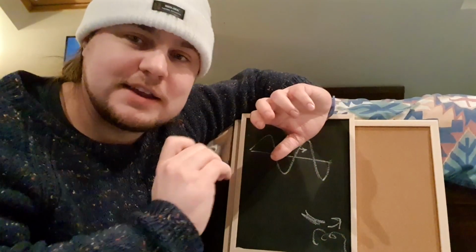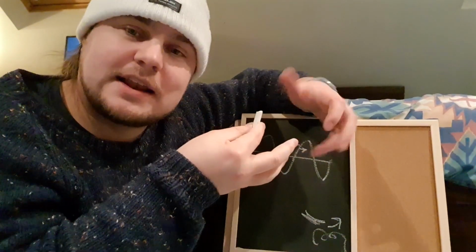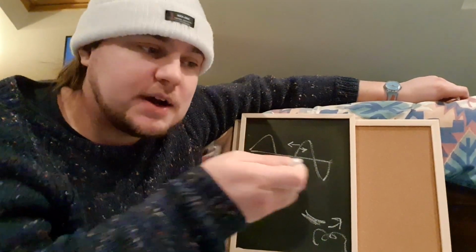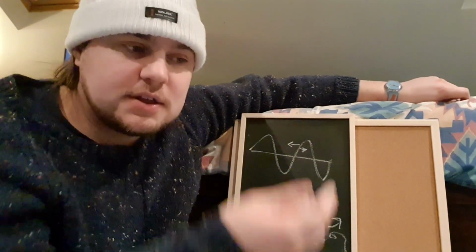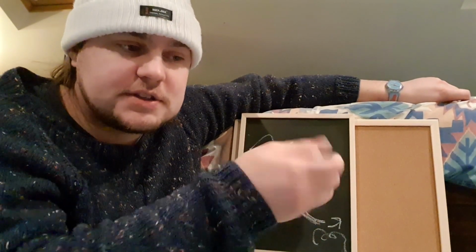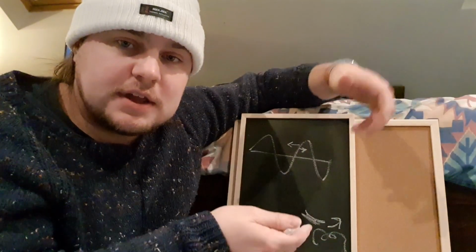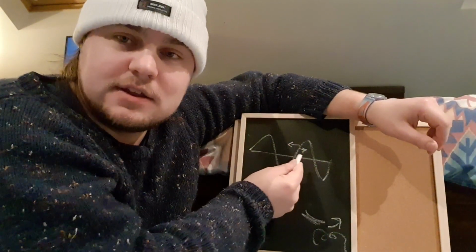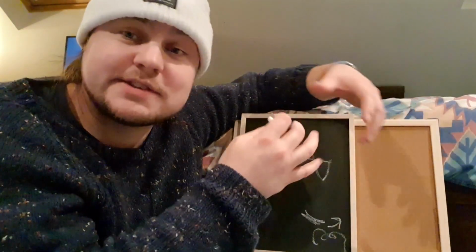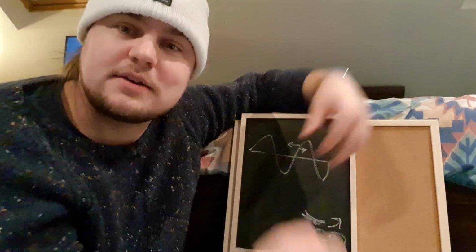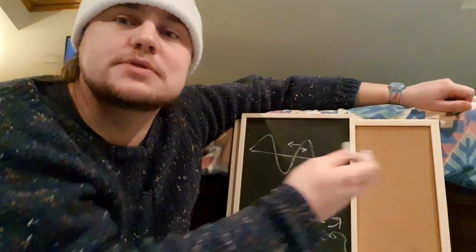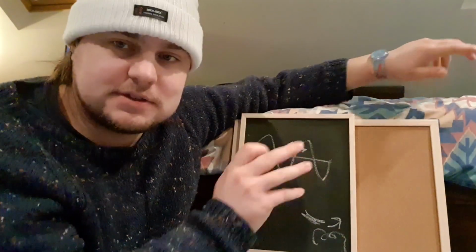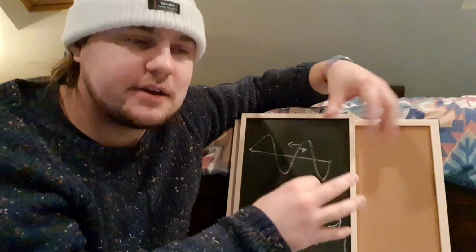So there's a balance between heat in, which creates movement, and electrical resistance. That means that if a generator, you turn the heat down on the boiler, the turbine would slow down and the power station would slow down, but it would be magnetically brought back into line. But because it would be continually slowing down, it might slow down all the power stations by a tiny amount, because it'd be creating drag on all of them and they'd all start to slow down. So in general, they all aim to keep at the same speed so that they can all keep going together and neither of them drags the other one back.